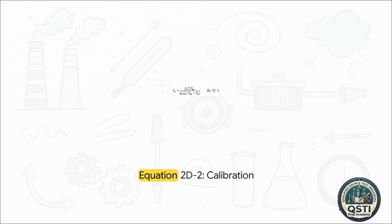And now, check out this next one coming to life on the screen. This is equation 2D-2, and you'll use this to calculate your test metering device calibration coefficient, Ym, against a standard reference meter. Ideally, you want to calibrate in the field with the actual principal stack gas you're metering, like air or nitrogen. A calibrated dry gas meter is totally acceptable as a reference here.